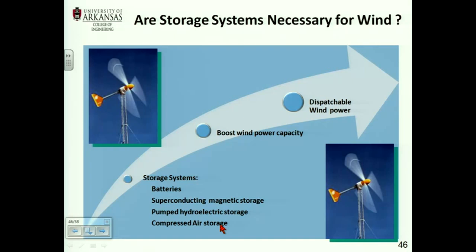It's not that you can cap the cave and come back in a week and use it. So normally you do it at 3 a.m. in the morning, you fill the cave with compressed air. It also doesn't have to be a big one, because otherwise you need a lot of air to build pressure. And then you use it at 5 p.m., 4 p.m. So you have basically a 12-hour cycle.